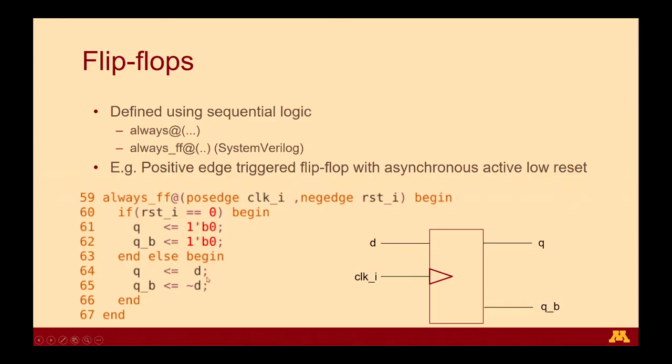And in terms of data flow, if this is a simple flip-flop, you can always combine a data flow model here by driving the input based on some data flow object. So for example, instead of driving just directly the D pin, if you want the input to be the AND of two signals, you could write that as, let's say, A and B in this line here. I hope that answered your question.